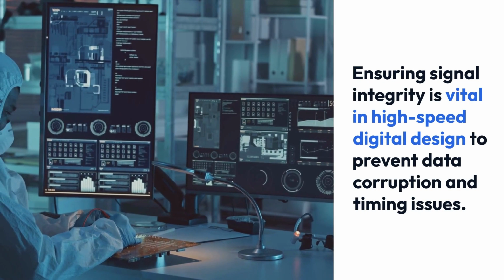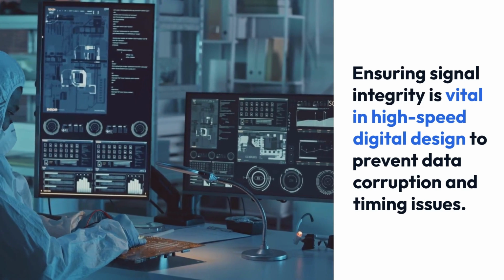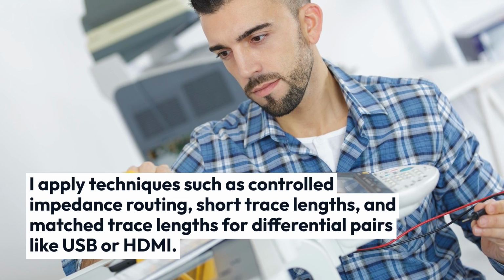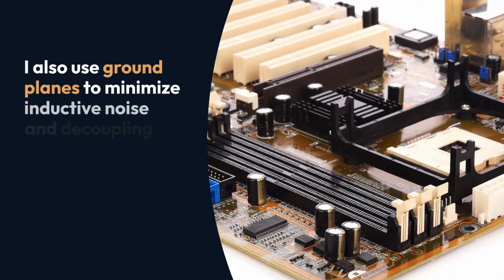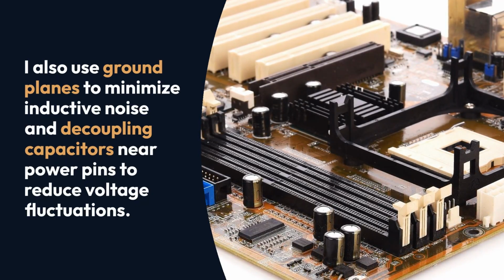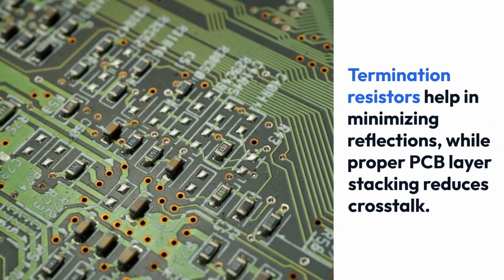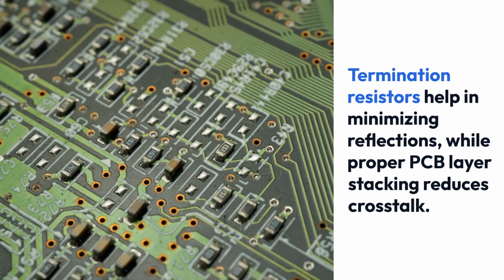Ensuring signal integrity is vital in high-speed digital design to prevent data corruption and timing issues. I apply techniques such as controlled impedance routing, short trace lengths, and matched trace lengths for differential pairs like USB or HDMI. I also use ground planes to minimize inductive noise and decoupling capacitors near power pins to reduce voltage fluctuations. Termination resistors help in minimizing reflections, while proper PCB layer stacking reduces crosstalk.